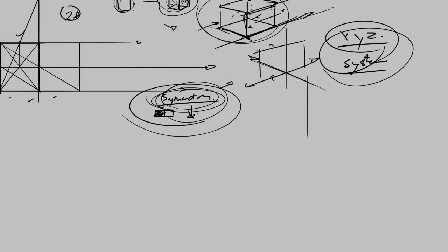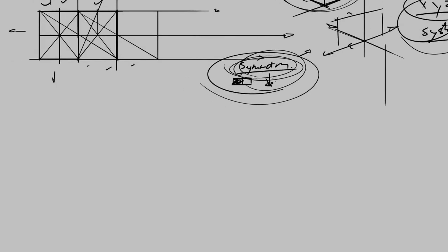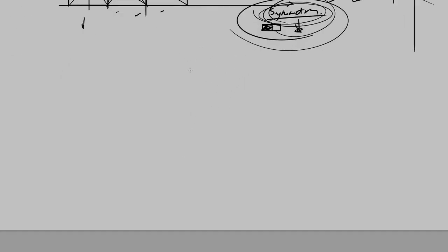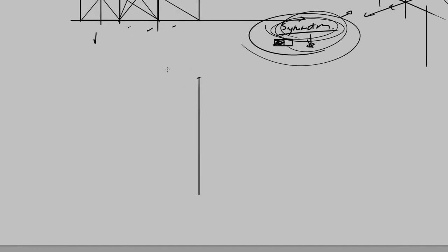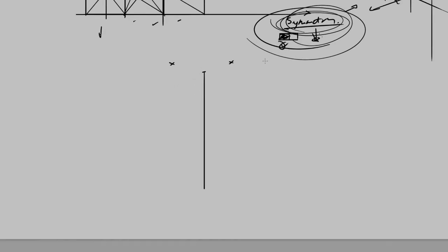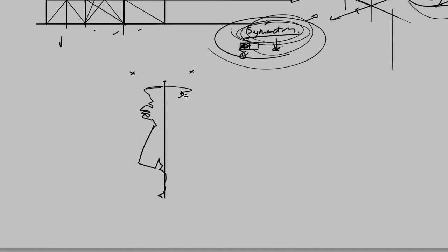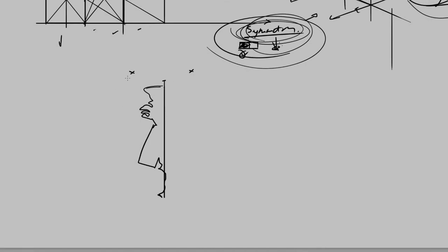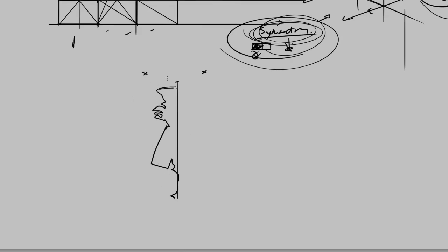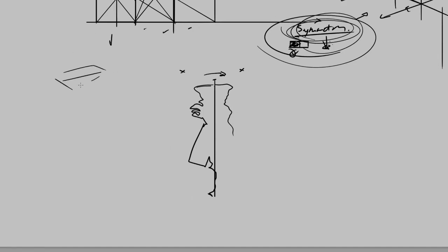So the next thing that I want to do is, I think of this line as the symmetry line. So let's first just draw this line. Symmetry is what happens on this side, I can do on this side. So if symmetry is on, immediately I know that I can actually just design one of these sides. And then in 3D software, the other side will be rendered directly as you work, or you have the option to select it and say mirror in this direction, and then you will get the exact thing copied over.